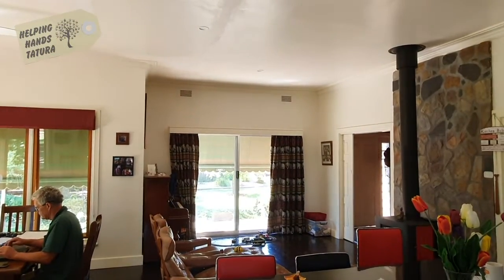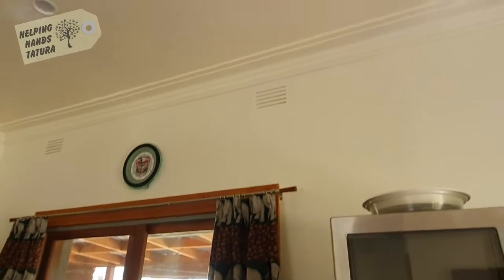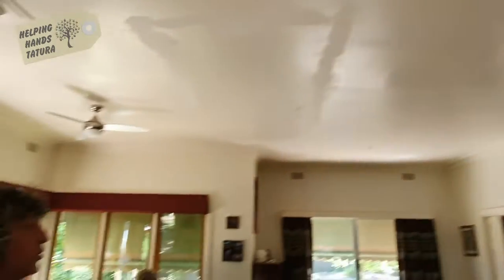Now these wall vents are part of the legacy of when houses were built. It was mandatory up to about 1980, 1982, that you had to have permanent open vents. And this was because historically houses had gas lights, but they also had unflued gas heaters. So the concern is that you do not want a build-up of carbon monoxide in a house. So the important thing is that the houses were designed to have permanent ventilation.